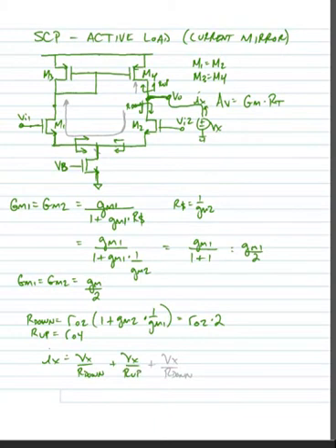But what we're going to find is when we cause a current to flow down through this device, because the current source here is a high impedance, all of the current that flows down through the device flows up through M1 and into the current mirror M3, which causes current to flow up. So we get another Vx over R down here.